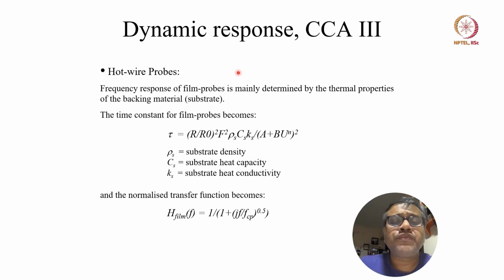The frequency response is mainly determined by the thermal properties of the backing material. The time constant of the thermal probe is given by this large expression, where rho s is the substrate density, this is the substrate heat capacity, and this is the substrate heat conductivity. So the normalized transfer function becomes what we showed earlier. So this is the one.